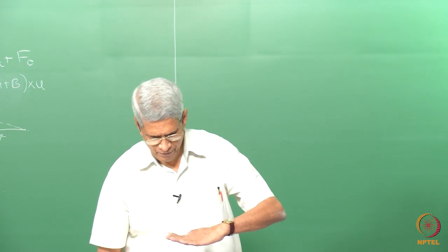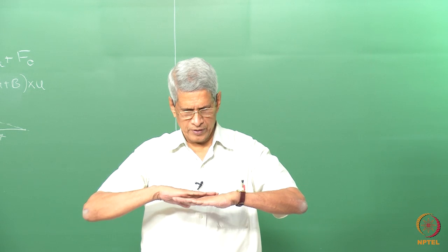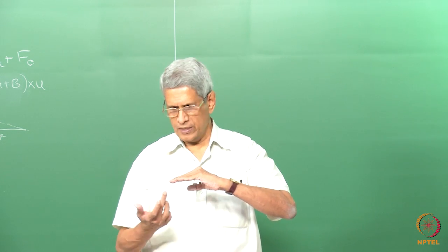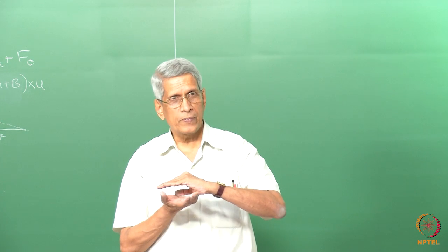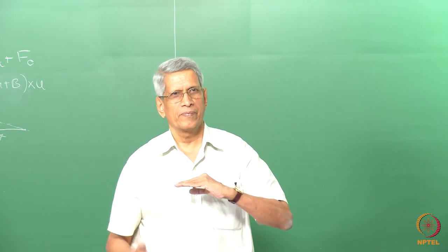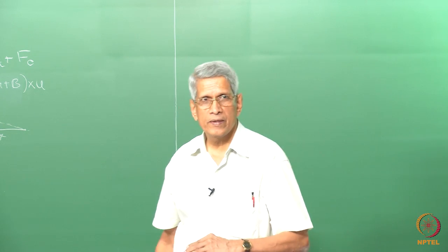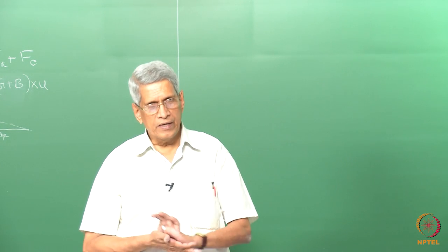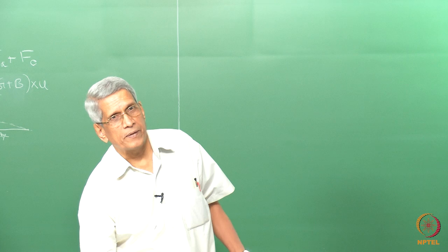So essentially when we look at it, now we observe that this has bent like this. The edge part is still in the slip plane, whereas the screw part of the dislocation has just climbed up. This is what will happen in the case of a mixed dislocation.